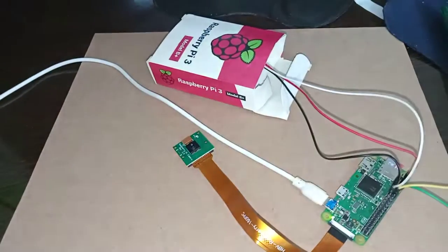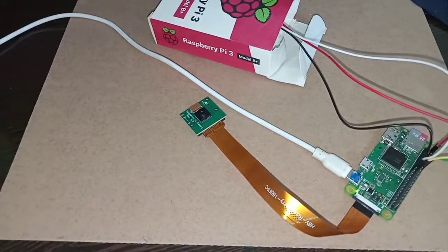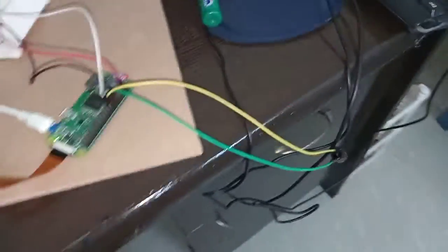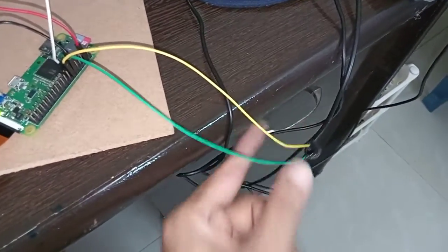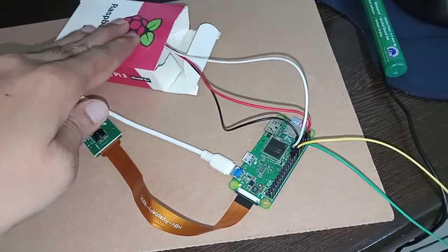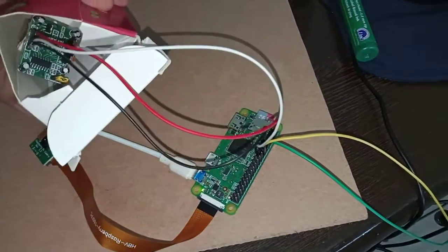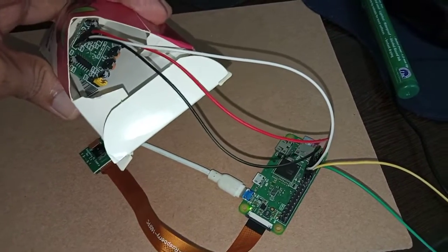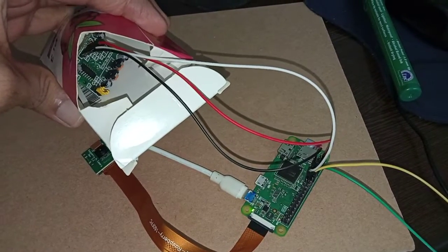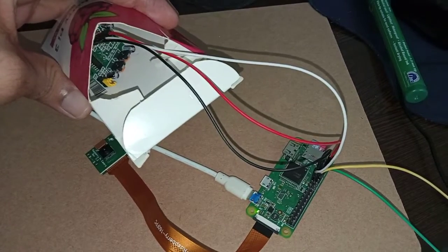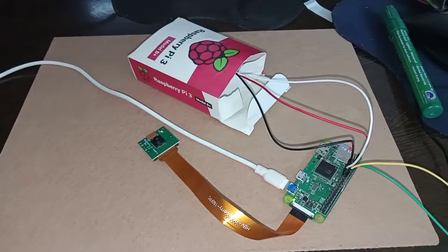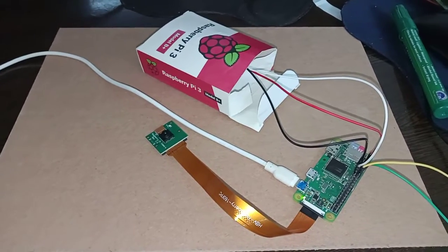So this project demonstration is of Intruder alert using Raspberry Pi and the Pi camera. Here you will have one buzzer and one PIR sensor. The PIR sensor is kept inside a box. You can use any box to avoid the movement detection happening frequently. Else, before you start the kit, the movement detection will be done continuously, and it keeps on sending the emails.